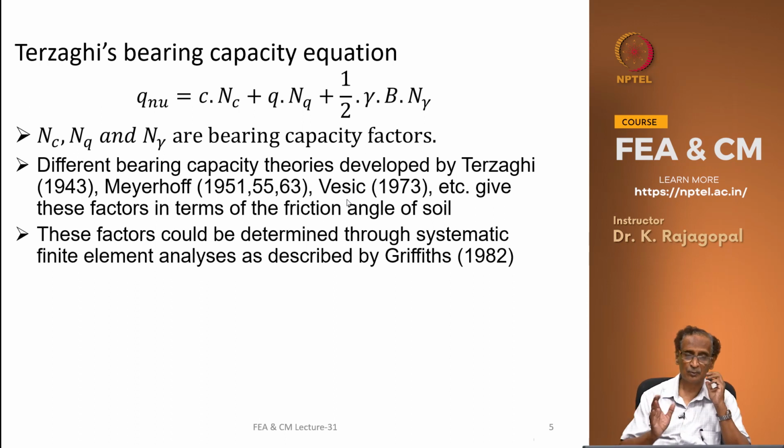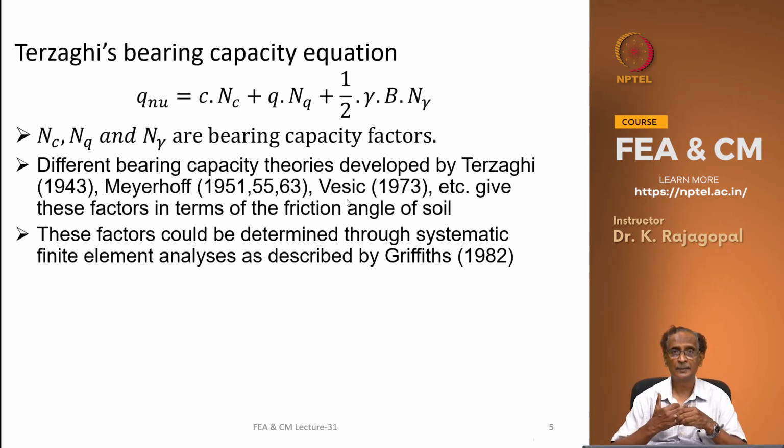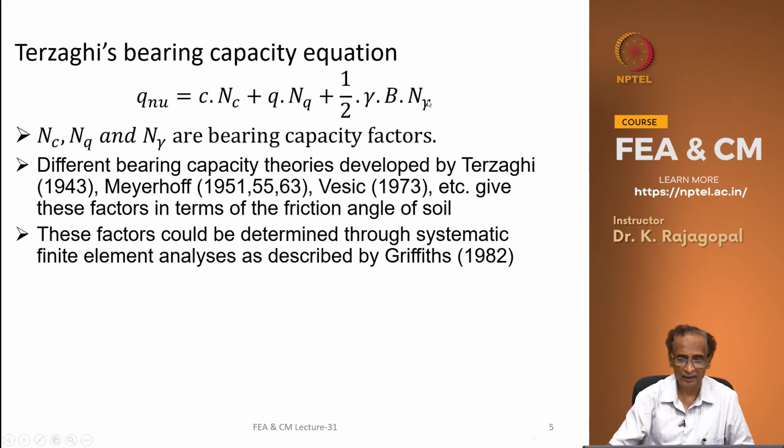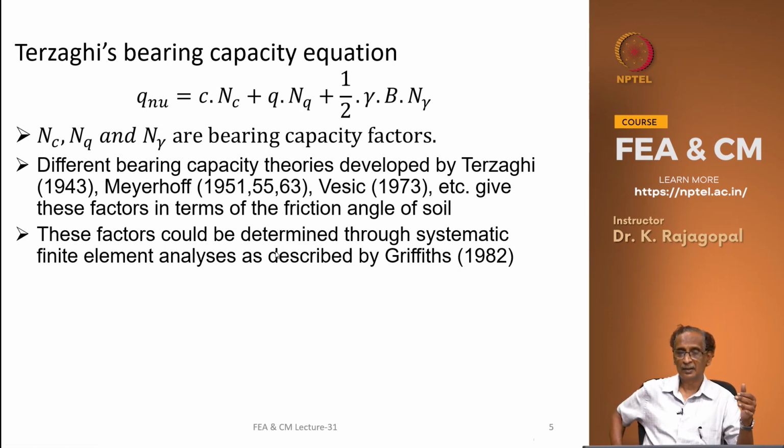And in this lecture I am going to only demonstrate the bearing capacity determination for a strip footing and for a circular footing. And these factors N_c, N_q and N_gamma can be determined through systematic finite element analysis as described by Griffiths, and I am going to describe that now for all of you.